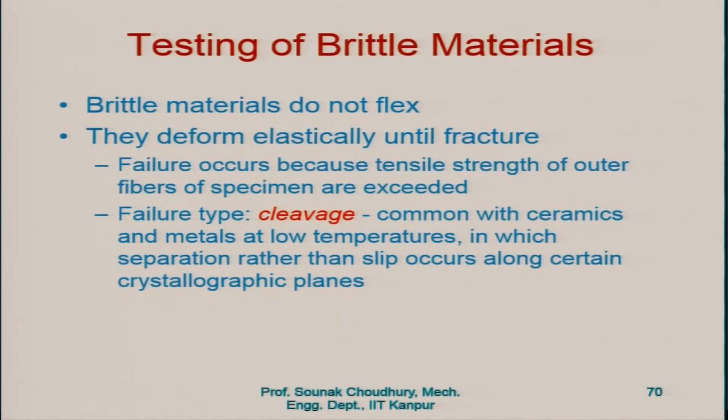Now, slip is the plastic deformation. Slip occurs when plastic deformation occurs along the slip line. Now, here it is a separation. So, that is why the failure is called cleavage. All right. This is commonly applied for ceramics and metals at low temperatures.